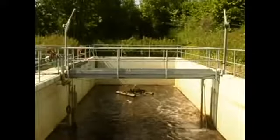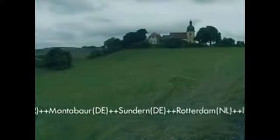The use of the OLOID has, according to its operator, decisively improved basin biology thanks to the constant, even, and high oxygen input. In addition, the OLOID aerator replaced 2 injector aerators with a 7.5 kilowatt output each, which enabled substantial energy savings. Another example of an OLOID system implementation is the Eschenau Pond Clarification Plant in the municipality of Knetzgau, Germany, which before had no aeration system.